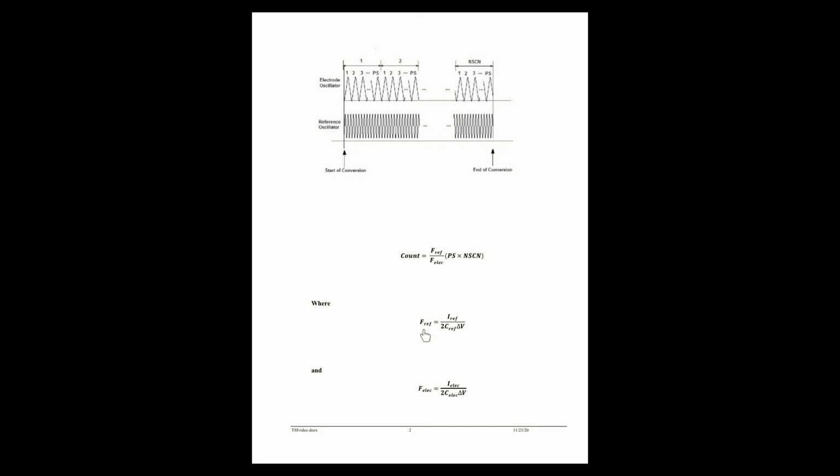So it's the same with the electrode. This is the reference, so it has this reference capacitor and this reference current. And then we have here the electrode one. This is the one that's going to change because it changes with this capacitance, which is the capacitance of the touch.